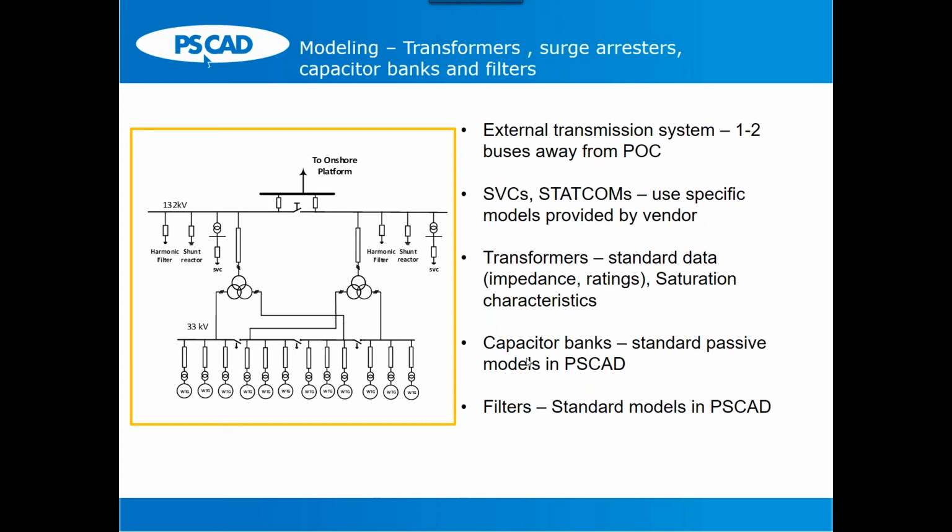They are important though, because the TOV problem is wind turbine current feeding into cable or other capacitances. So how filters and capacitor banks contribute to that overall capacitance, depending on your scenario, depending on the breakers you switch, and depending on where your filters and capacitors are. So you need to represent them.